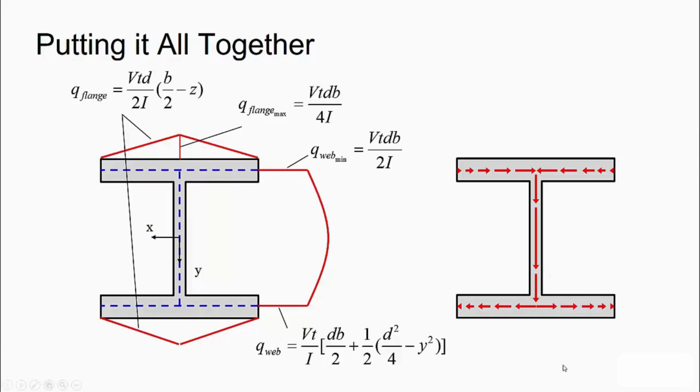Now, the interesting thing to keep in mind in future problems is that property of the shear flow combining, so that you can double check your work: when you have two shear flows combined into a single one, you should be able to add those magnitudes to check your work.